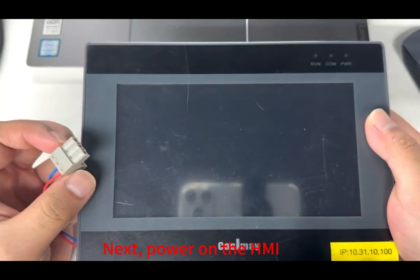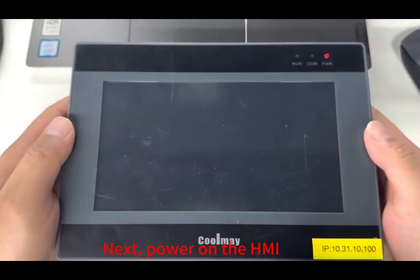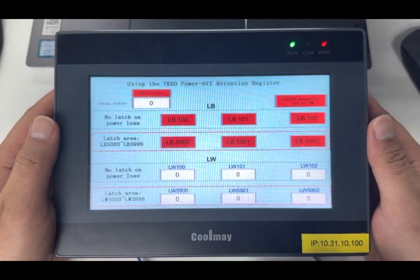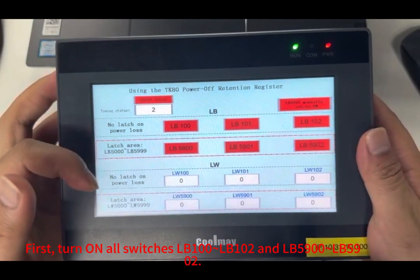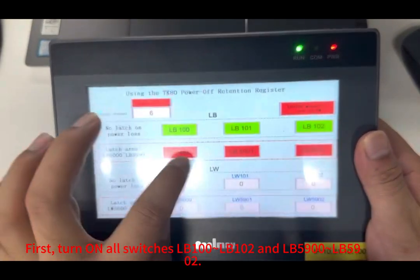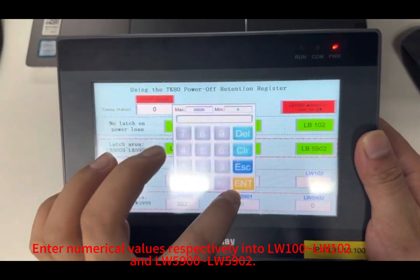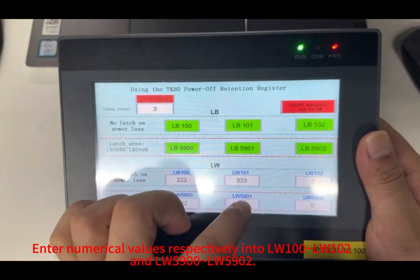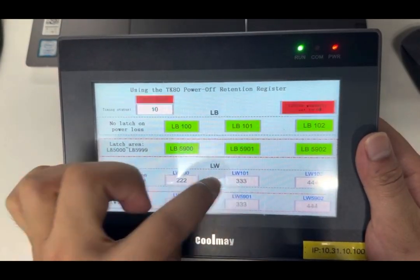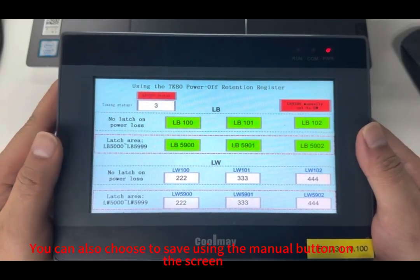Next, power on the HMI. First, turn on all switches LB100, LB102, and LB5900, LB5902. Enter numerical values respectively into LW100, LW102, and LW5900, LW5902. You can also choose to save using the manual button on the screen.